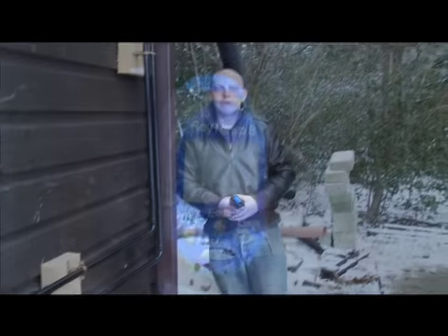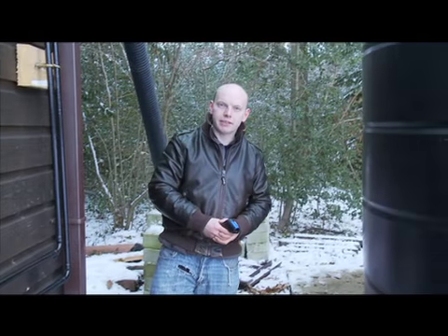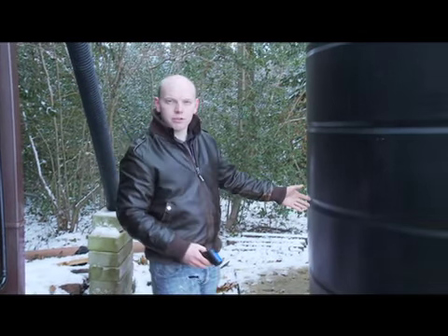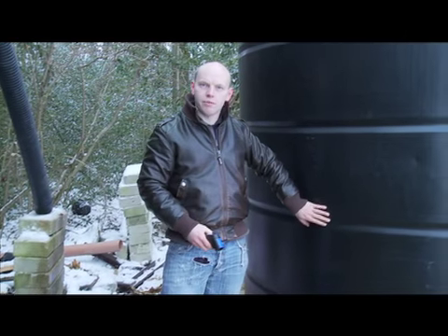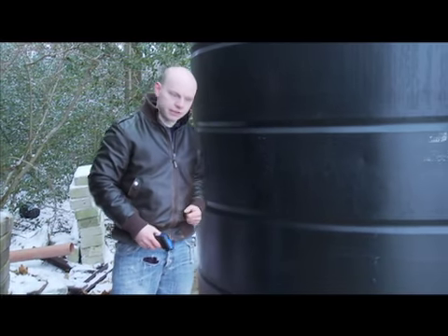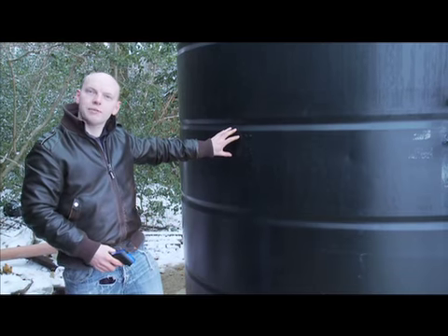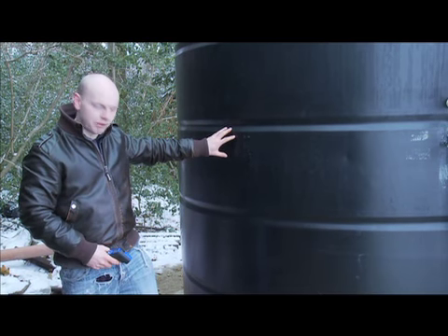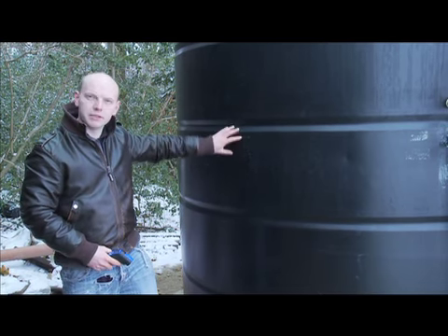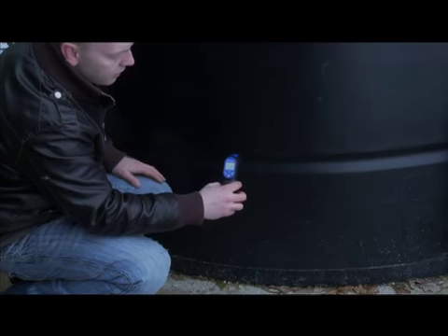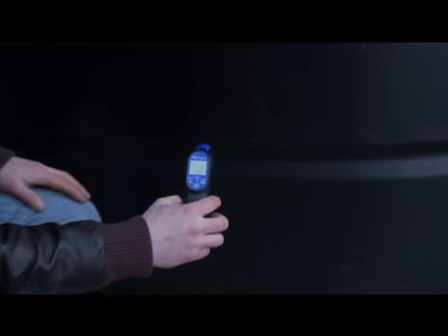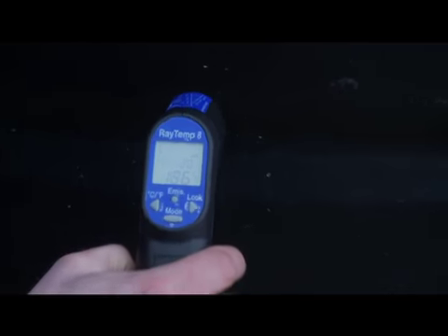After we picked up the heat from the ground and put it back into the condensing matrix, we use this water tank here as a supercooler to remove any excess heat from the refrigerant to allow this process to complete. This tank was set at ambient, which is about freezing at the present moment, and over the last 5 days has heated up with the excess heat, which has currently risen to 18.6 degrees centigrade in a 10,000 litre water tank.